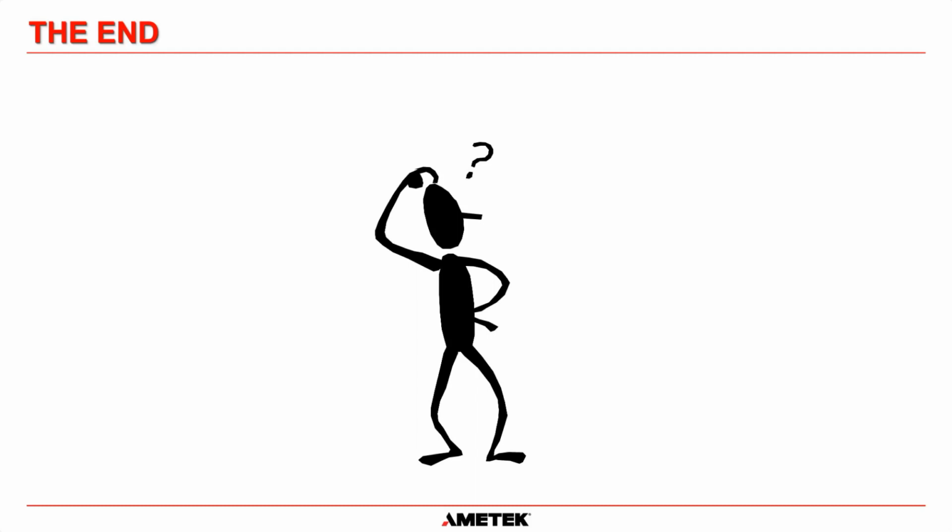And if you rule that out, then pretty much it's either going to be that the control board that's monitoring the AC is faulty, or it is the cabling between where it measures the AC voltage and the control board. There could be a loose connection there. So that's the three things I would check. First of all, make sure you're not having an actual AC occurrence.